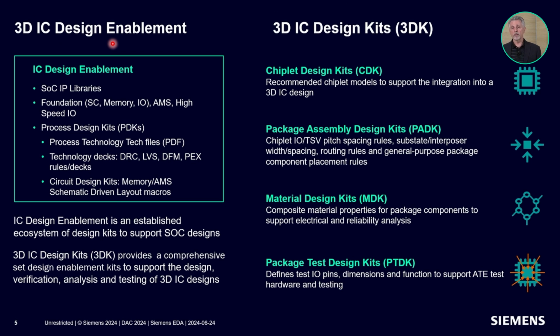So we're trying to extend that concept for a lot of the things in the packaging world, but it is a different type of set of design kits that are required. So 3D IC design requires a comprehensive set of design enablement kits to support the actual design, verification, and handoff to manufacturing. We call them 3DKs for short, and we have different areas listed on the right. So the CDK I just talked about, and I'll go through a little more detail of what's in there, is done. That's an existing standard.